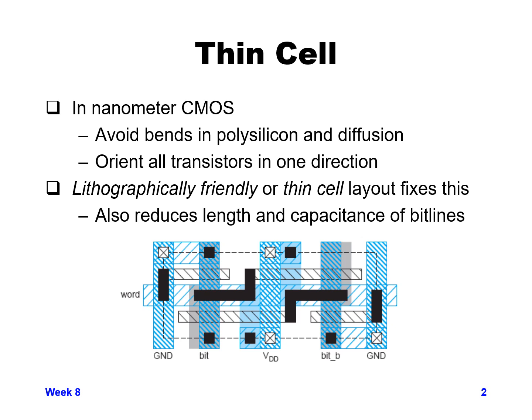Reducing length reduces resistance and capacitance, both internal to the cell and of your bit lines. So this is used by various different players in the industry in order to compact the size of their bit cells as much as possible.